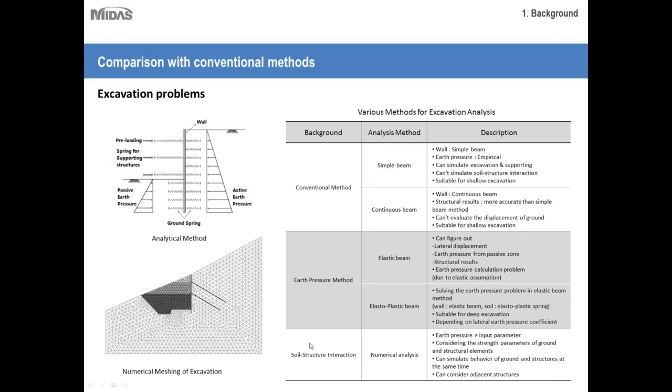And then for soil structure interaction, which is the highest level of analysis for excavations, as you can see, it's done with numerical modeling programs, and it can consider adjacent structures. Say you're doing an excavation, but there's a nearby structure, and you want to ensure that your excavation doesn't significantly reduce the stability of that foundation. You would need to do a numerical analysis, because neither the earth pressure method nor the conventional method would be able to account for that.